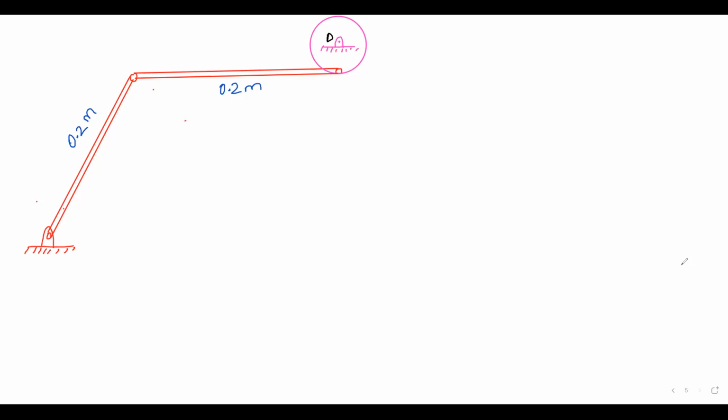Now write AC one more time using point B, I'm sorry. So AC equal to AB plus something, and you will have alpha CD scattered in that equation. Equate the AC that you are getting using this point and using this point. So you will have a very big equation that will have alpha BC and alpha CD scattered. You have one equation with two unknowns, but technically I with I and J with J will give you two equations with two unknowns. Boom, game over. Okay. Thank you.